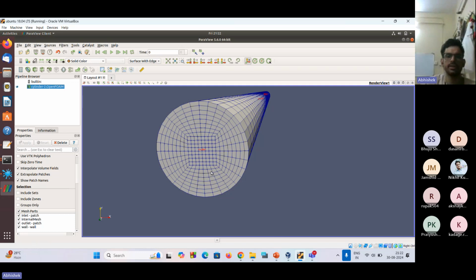So there are various cases in which we have to define a multi-block system, maybe 8 blocks. If you also simulate flow over a cylinder, a circular cylinder, you have to make maybe 16 to 20 blocks. So we always have to define a multiple block system.